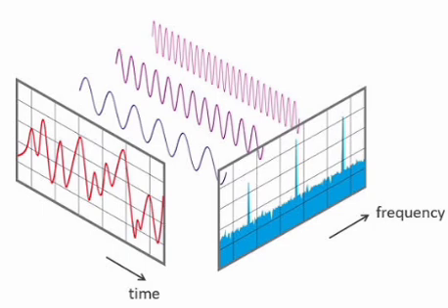ROC is the region of convergence: the values of z for which the summation over n from minus infinity to infinity of x[n] z^(-n) converges. Properties of ROC: the ROC of X(z) consists of a circle in the z-plane centered about the origin. The ROC does not contain any poles.